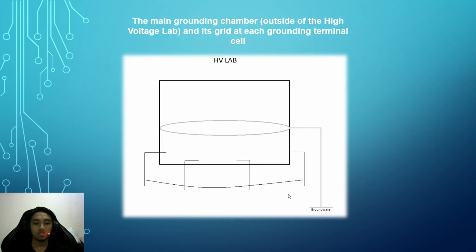Under the wet condition, we can get around below 1 ohm, while under the dry condition, we can get around below 2.5 ohm. According to IEEE, if grounding is below 5 ohm, it is acceptable, which means it is good enough to be a grounding point.